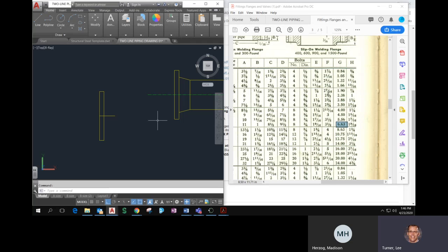Now, when you make your 3D, you're not having to hollow this out, but go ahead and let's make it 6 5/8. Now, here's kind of the center line, and so I want to go half of 6 5/8 to the top and half of 6 5/8 towards the bottom. So I'm going to get my calculator out in my head, and I'm going to do this math. Half of 6, the whole number, is 3. Half of 5/8 is 5/16. So I'm going to go offset 3 and 5/16. If you can't do that in your head, get a calculator, no problem.